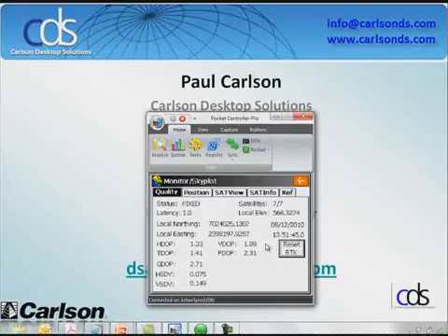Reset RTK does essentially that same thing in that it tells the position to start over, forget what we just did. But the big difference is doing it here makes a clean cut. So instead of saying, well, we'll dunk it and flip it and hope that there's nothing bad in there, using Reset RTK completely clears out that previous record and starts fresh. So this was a phenomenal addition by Carlson to add that in, at least in my opinion.